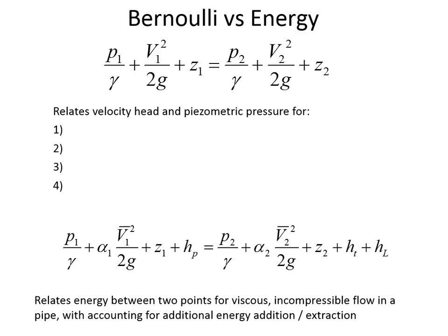In reality, yeah, it matters because, for example, if we put the pump all the way at the end, then there could be cavitation because maybe the pressure is decreasing as you go through the pipe, because of friction losses. If you have the pump at the end of a very long suction side, if you have too much length on the suction side, then cavitation can occur.